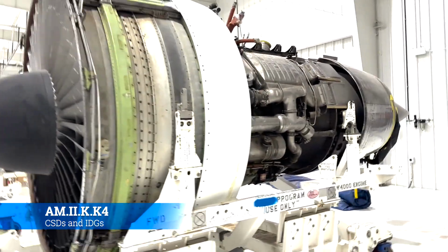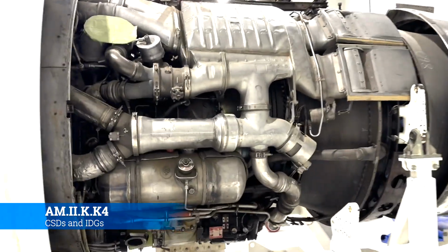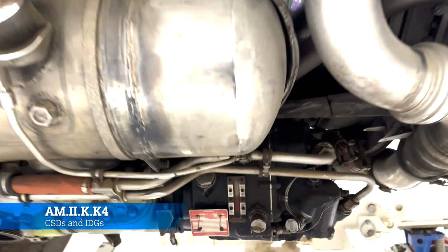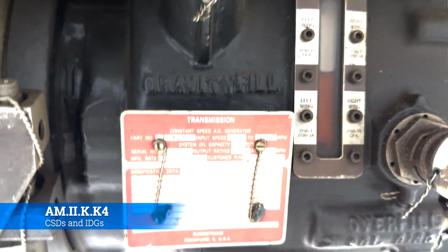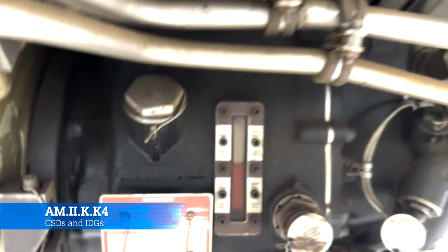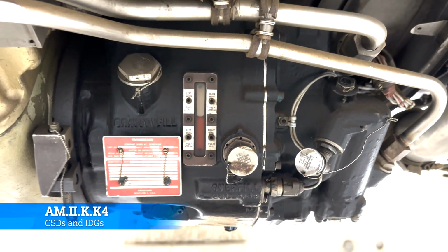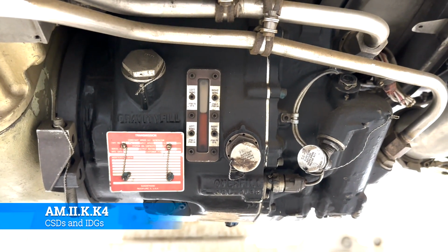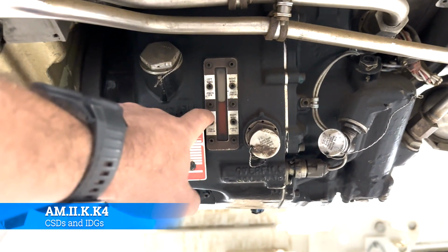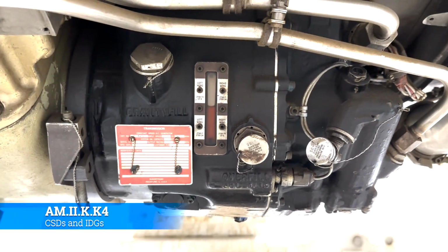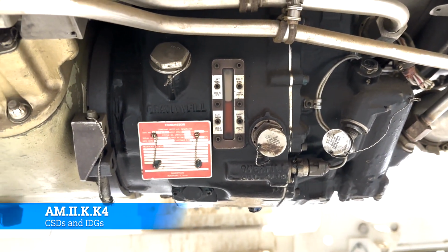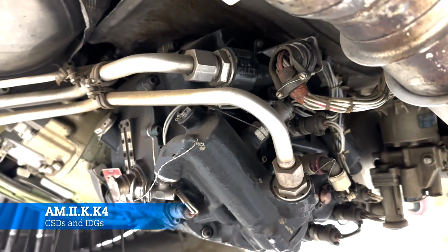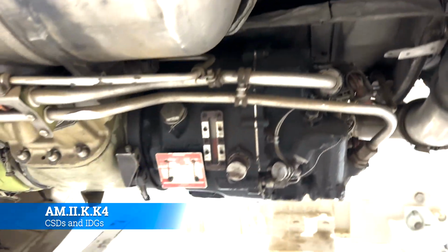Okay, here we have a JT9. This is used on the 747, and the 747 has a lot of electronics. Right here, you'll notice the CSD. It'll be the constant speed AC generator. Notice that it looks a lot like a helicopter transmission or something that has a sight glass that needs to be filled and serviced on a regular basis. So that's something that, if you're doing a pre-flight or returning an aircraft to service, you'll have to take care of on a regular basis. But that is what a real-life CSD looks like.